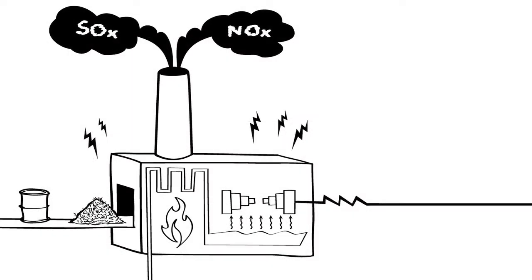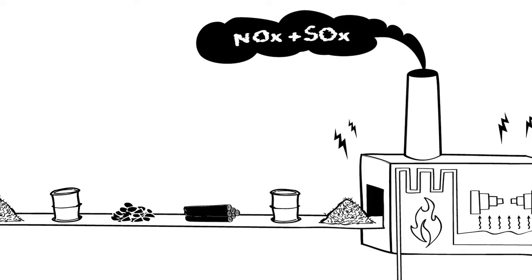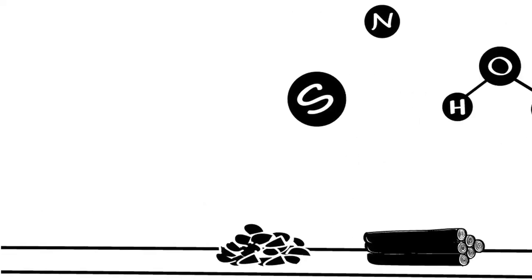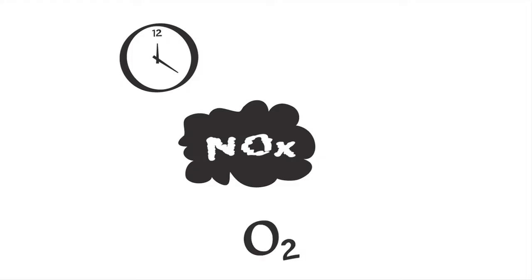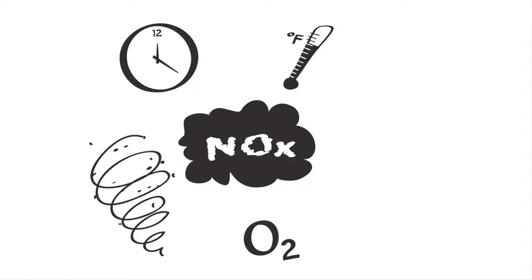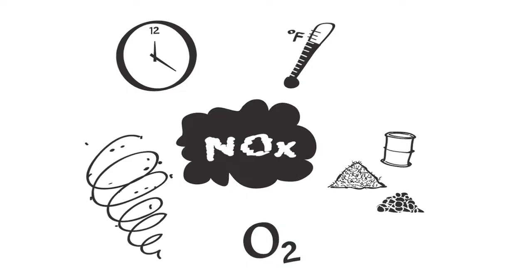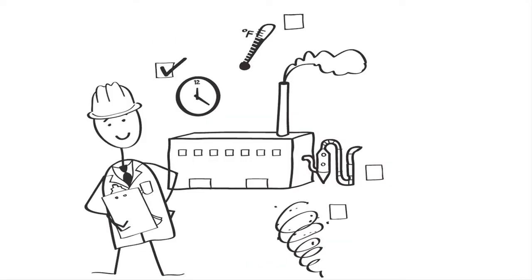In the pulp and paper industry, the majority of both types of emissions comes from power boilers used to generate steam and electrical energy for the manufacturing process. The most important determinant of SOx and NOx emissions from power boilers is the choice of fuel, by virtue of its chemical composition and combustion properties. NOx emissions are also greatly influenced by the conditions of combustion. Therefore, both fuel type and combustion conditions need to be looked at in terms of NOx emissions reduction. Recommendations for emissions reduction include practicing prudent combustion practices and the selective application of post-combustion controls.